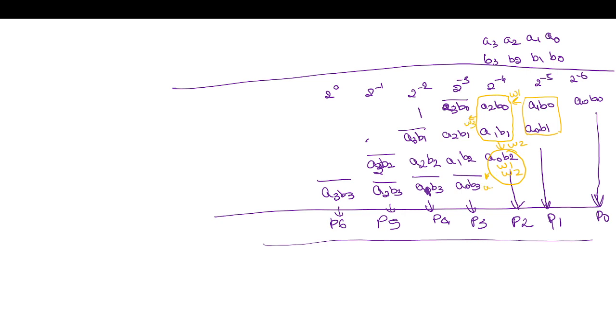This will have an output W6, because if we have considered this, then W5, and then this will have W4. The same way you can combine with half adder plus full adder. So this Baugh-Wooley multiplier architecture requires 8 half adders plus 7 full adders. Optimum design.